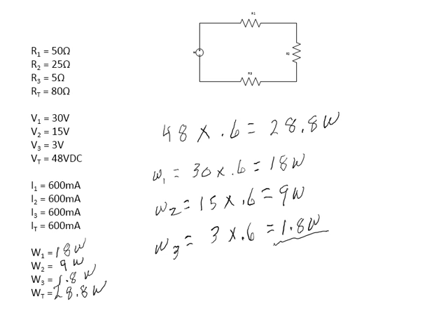And again, you can check your math here by adding up the sum of the power dissipated by the individual resistors, and it will equal your total wattage for the circuit.